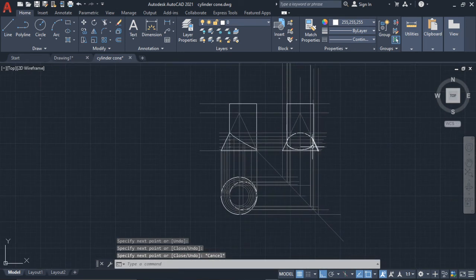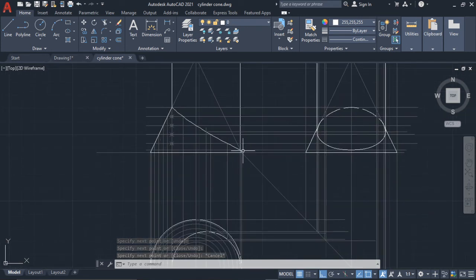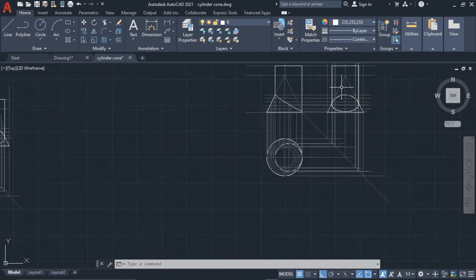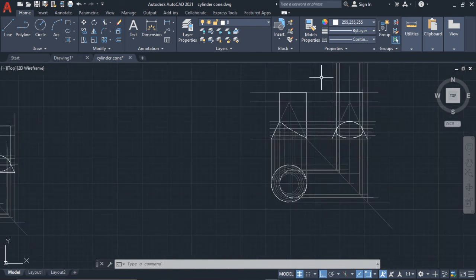Now, I'm going to do this because what we'll see here is how this looks from the right side. So this is the right side view, but this is first angle orthographic. So the left side would actually be here, and the right side would be over here. So I'm going to change this to make it look like the left side, because the left side should be here, but it's going to require a minimum amount of change. So I'm just going to do this.